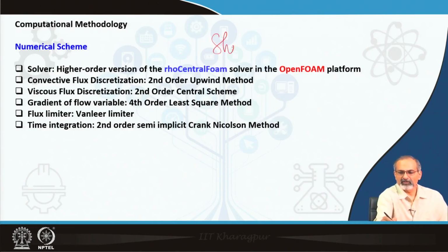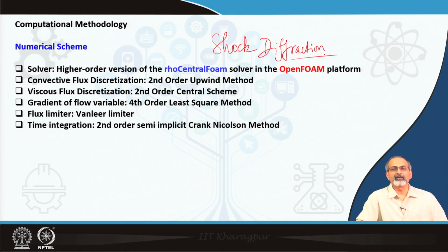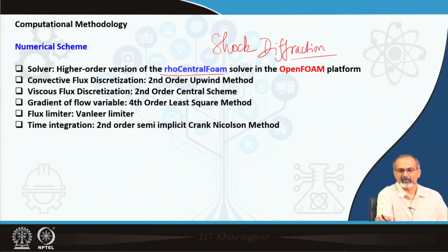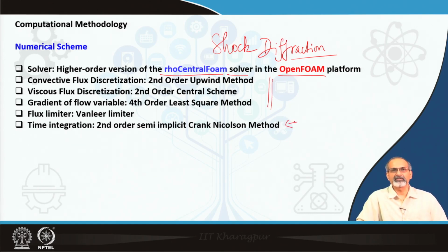As far as the shock diffraction problem is concerned, we give some details about the solver and schemes that we have used. We have used the rhoCentralFoam solver in OpenFOAM for performing this exercise. The different schemes that have been used, where some improvisations also have been made by the research team that we have. The last one in particular, implementation of a semi-implicit Crank-Nicolson method for time stepping the solution.